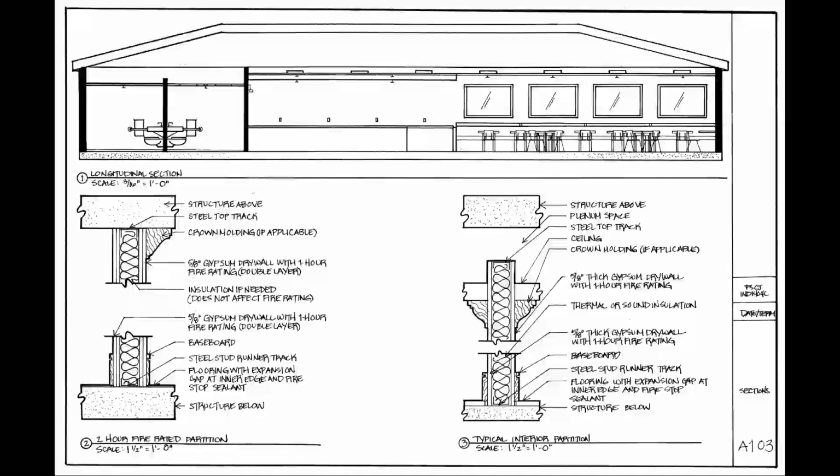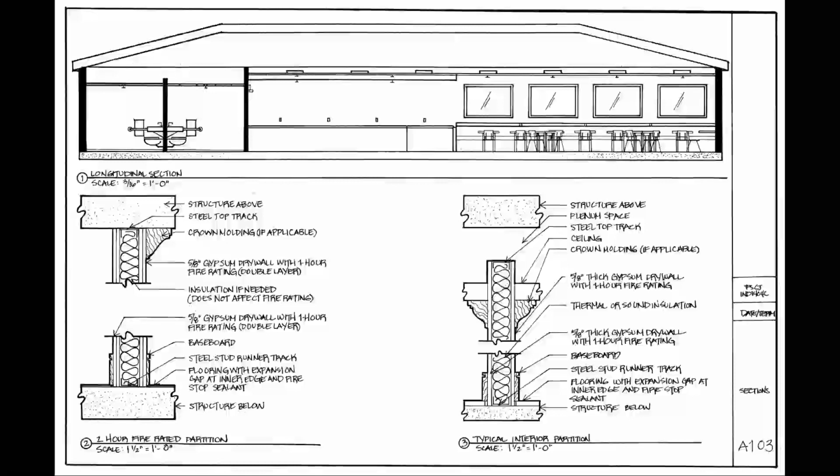So with that said, let's zoom in a little more on the particular drawings on this sheet. Let's begin with this longitudinal section, which is one way of talking about the long cut through a space. If I had run my section cut vertically instead of horizontally on my floor plan and looked either to the left or to the right, that would have been considered a transverse section. It's a little bit shorter and doesn't really show the full space.